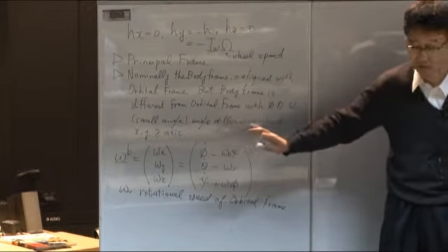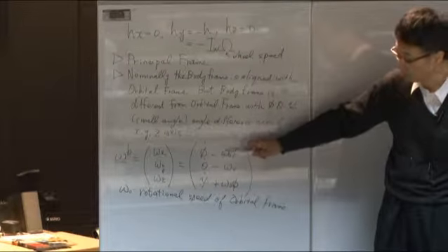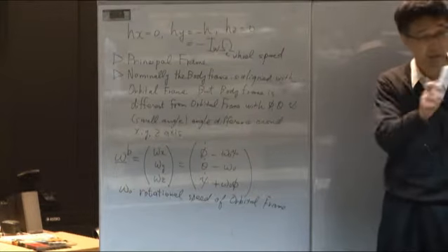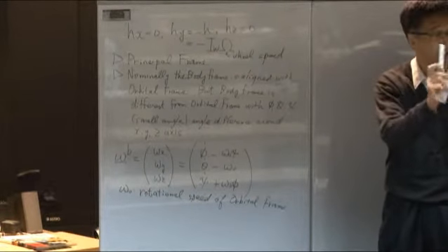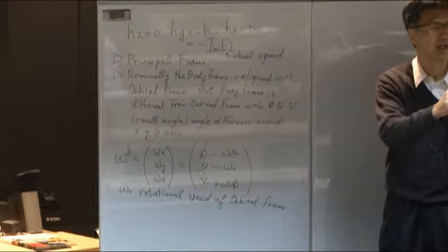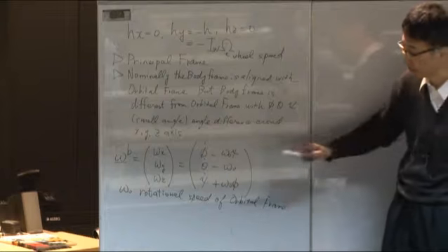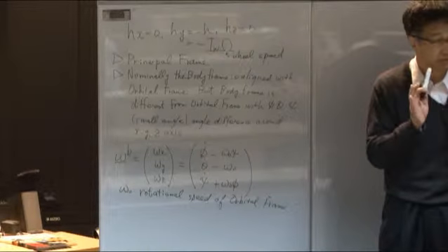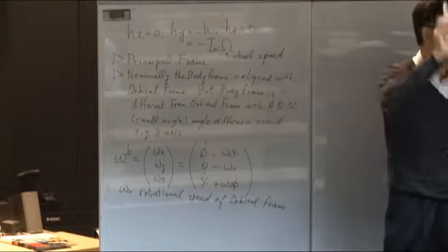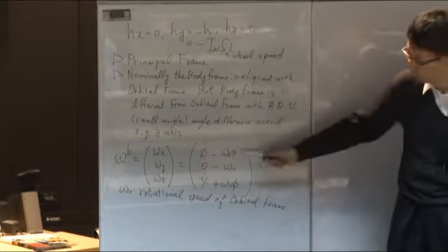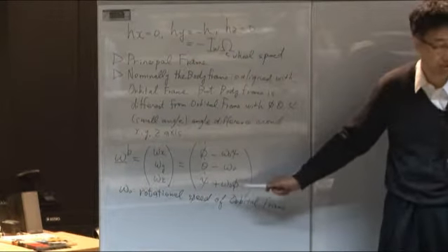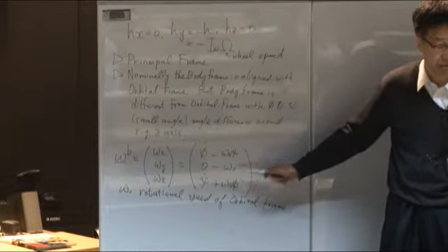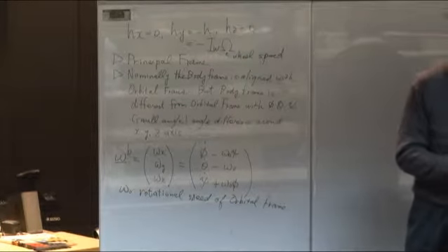For the spinning satellite case, spinning around the y-axis makes a coupling of the x and z-axis. But in that case, this rate is very fast. The spinning satellite rotates something like one rotation per 1 second, or maybe 10 seconds and so on, very fast, and so the coupling is much stronger. So please consider that. If the satellite rotates around the y-axis, then the x and z-axis will have some coupling, and the coupling strength depends on the spinning speed of the y-axis. That is a very basic characteristic of the spinning satellite.